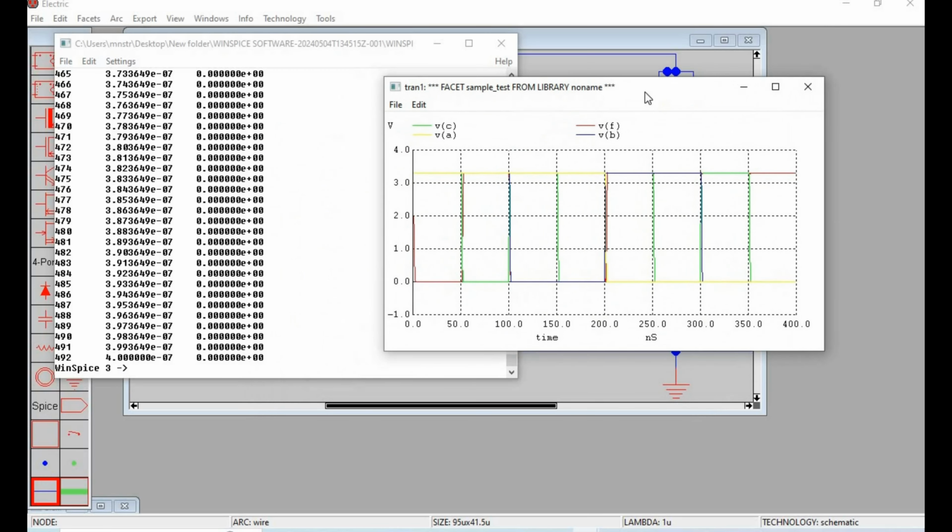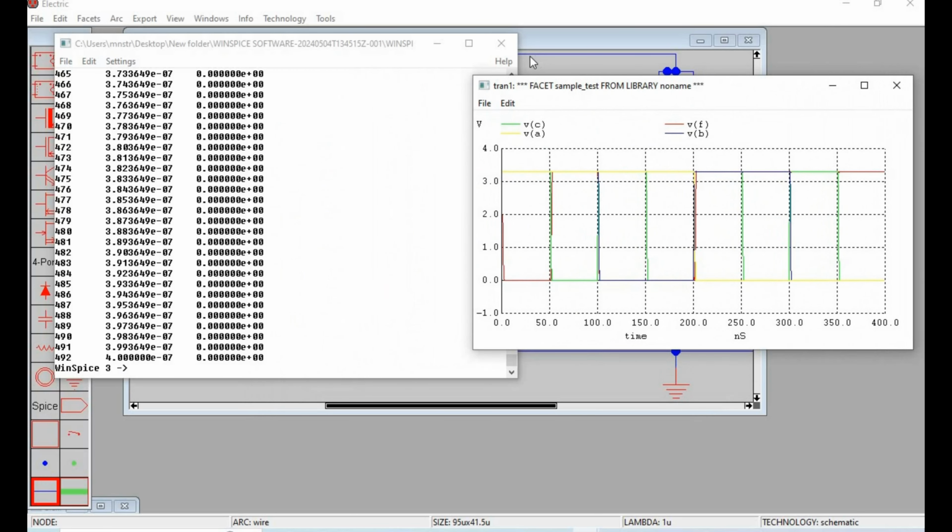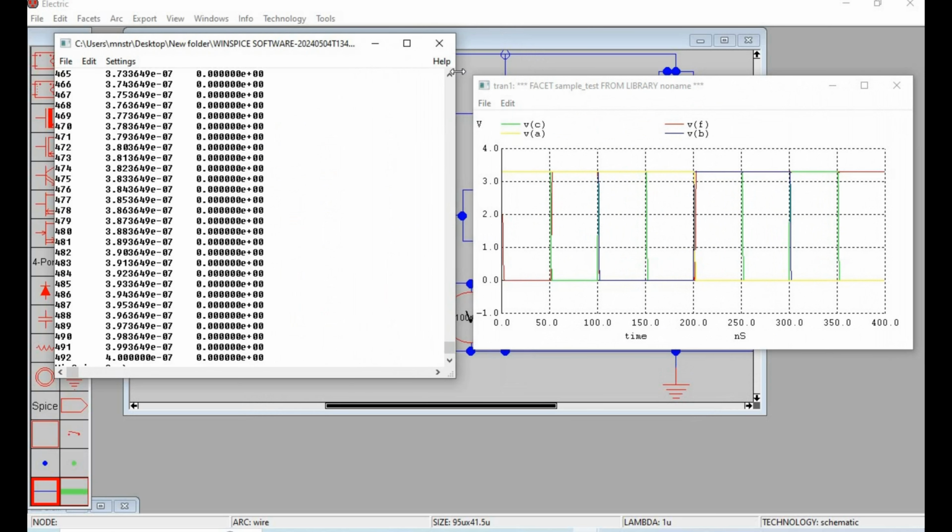You will notice that all plots are on top of one another. For you to arrange it, the topmost part should be the most significant bit, and the lowermost part is your output. For you to be able to do that, use the command plot, start with the output VF, then since our supply is 3.3, use a greater value for your step size.